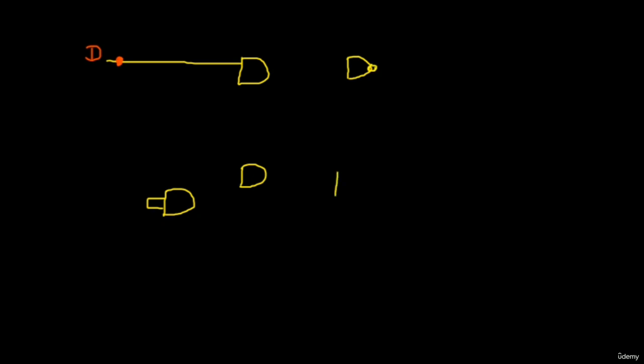Well, now let's proceed to the design part and let's design our D flip-flop. To design our D flip-flop, we just need one input. So let's make our one input first. This is the D, which is our one input. And now here we are introducing our first AND gate. And now we also want the clock. So let's make our clock. First of all, let's make all our AND gates. This is one of the simple practices: whenever you learn it and you have to make it, just remember how many AND gates or NAND gates you are actually using. That's all you want. Because once you learn that and perfect that, you can make the connections easily. At least it becomes a little easier to perform certain actions in various practices.